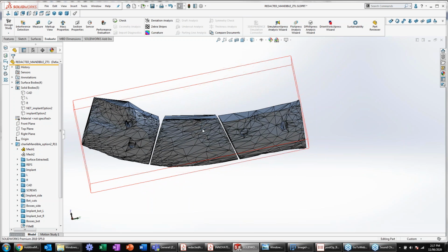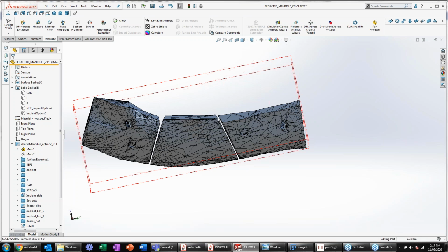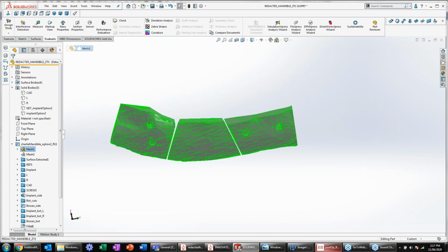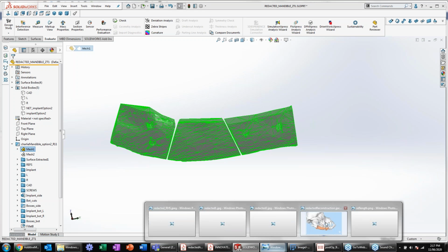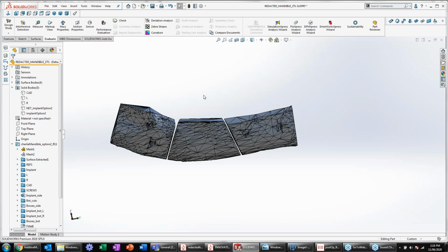So between the veterinary surgeon and us, we decided what part he wanted to fill up with titanium. So that's that center part here. And then we gave ourselves some references around the outside of where we were going to design the bone plate. So the first part was getting that mesh. So from the bone, we basically extracted the part of the STL file that we had got from the CT scan, and then we put that into SOLIDWORKS.